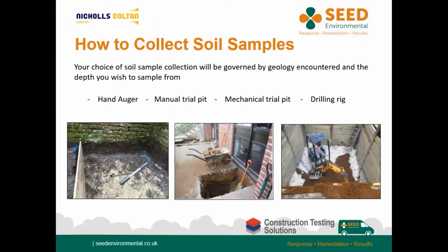So, how do you collect soil samples? Essentially, soil sample collection will be dependent on a series of factors, most fundamental being the geology you expect to encounter and your target sample depths. Based on the analysis you wish the laboratory to undertake, you'll also need to consider the sample volumes required and the container type, such as plastic or glass, based on the expected contaminants. Amy will cover this off in more detail in the presentation later. However, it's worth noting accredited laboratories like Nichols Colton will be able to provide you with the relevant advice and correct containers on request.